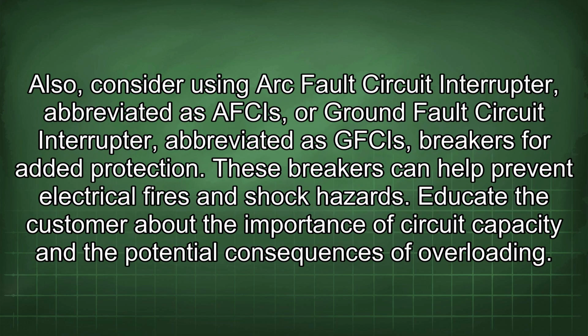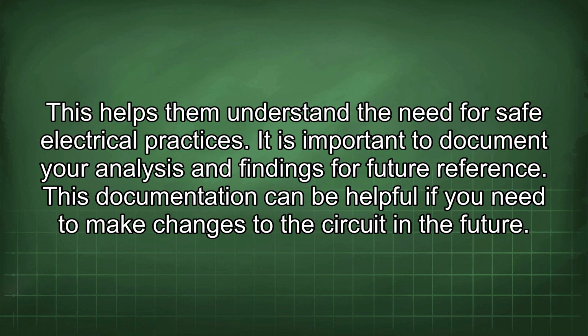Also, consider using arc fault circuit interrupter, abbreviated as AFCI, or ground fault circuit interrupter, abbreviated as GFCI, breakers for added protection. These breakers can help prevent electrical fires and shock hazards. Educate the customer about the importance of circuit capacity and the potential consequences of overloading. This helps them understand the need for safe electrical practices.